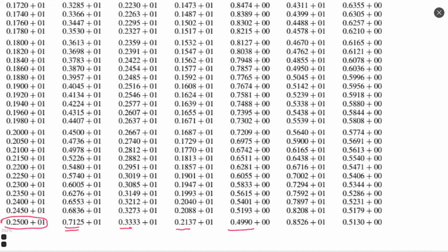This is why we cannot have a simple engine that would fly and generate considerable thrust at Mach 2.5. We need to have a sophisticated diffuser, like the diffuser you are trying to calculate in work 1. And for other parameters, the relation between stagnation pressure and static pressure before the shock wave, and Mach number after the shock wave is 0.51.